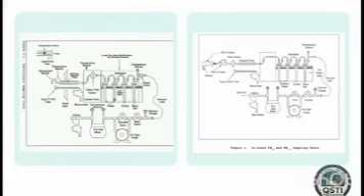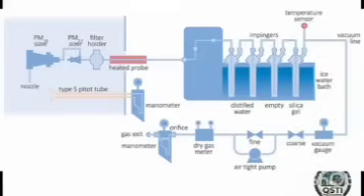And why is that? Well, because Method 201A relies on actual physical in-stack cyclones to separate the particles by size. The pure physics of those cyclones absolutely demand a constant, steady flow to maintain those precise size cuts at exactly 10 and 2.5 micrometers. If you mess with the flow, you change the cut size, and boom, your data's ruined. So Method 201A trades that strict isokinetic adjustment for physical particle sizing. You're aiming instead for a steady flow that lands at an acceptable 80 to 100% of isokinetic flow.